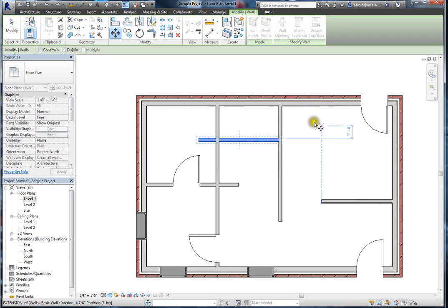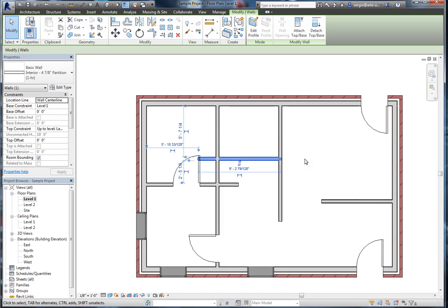So I'm just going to click anywhere. I'm going to click somewhere in white space. So that's my start point. And now look down here, it says click to enter Move endpoint. So now it's asking me where's your second point or your destination for this move. So I'm going to click, for example, right there. So we moved that wall from point 1 to point 2.